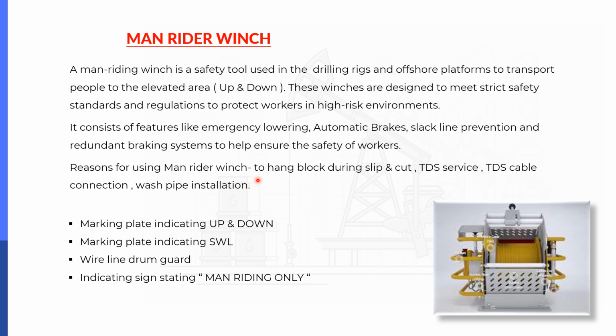Those jobs are the following: to hang the block during slip and cut, TDS (top drive system) services, TDS cable connection, wash pipe installation, etc. So whenever the rig people, for example the chief electrician or mechanic, have some maintenance job to do in an elevated area, or some other person goes up for maintenance or inspection, that is when the man rider winch is used.